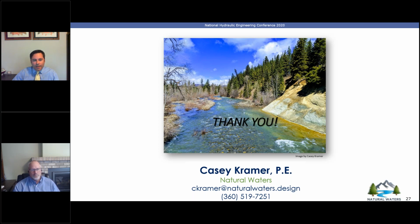That's where I think the concept of the one hydraulic model with the 2D, if you're able to develop a corrected effective or existing conditions that can replicate the BFEs and the water surface elevations at the effective cross sections, then you can use that 2D modeling tool to assess the change. But I'll state the obvious: make sure that you are thinking about what the model was originally developed for and whether that should be applicable to the analysis that you're trying to do in present time.